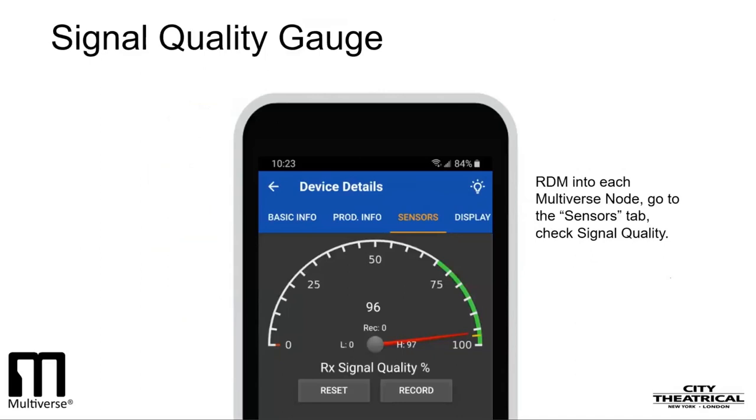When the gear is all in place, plugged, ready to test and evaluate, a simple way to begin is to check the signal quality of each receiver by using RDM with your DMXcat. This will be easier if you have used RDM to change your editable device labels to give them descriptive or numerical names, such as stage left multiverse node or multiverse node number 1. Once you've found the node you want to check, go to the Sensors tab and you'll see the signal quality gauge like the one shown here. If your signal quality is in the green zone, you have a good connection. You can work your way through all 18 multiverse node receivers this way, using your DMXcat app from your smartphone.